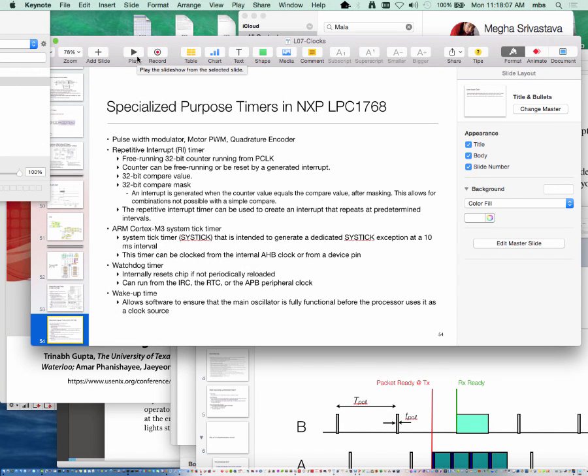The main point behind all this is that by the time you see timing information in a system like this, in a typical embedded system, there's a whole bunch of things going on. There is the resonator oscillator, whose imperfections you have to worry about. They're unstable and all. You have to set their frequency to the right thing. And then there is this interface, the suite of timers and things like that, which the processor provides. And then finally, at the highest level would be your operating system APIs, which let you read these things. So things like sleeps, things like wake me up at a certain time, all this kind of stuff which the operating system provides to manipulate this.